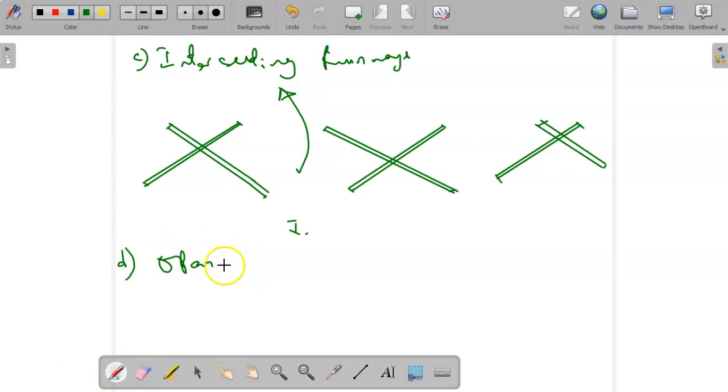Open V runways. For the open V runways, we said they are necessary when relatively strong wind blows from more than one direction. When we have relatively strong wind blowing from more than one direction, only one runway can be used, while in light wind, both can be used.